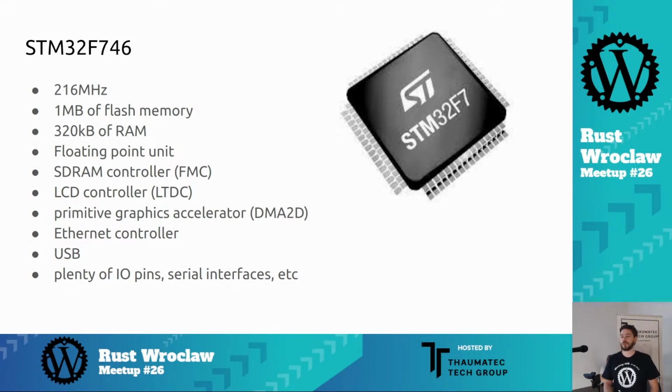So, for example, if you have an LCD with 16 pins to address the pixel color, you would normally use 565 encoding, which means you have 5 bits for red and 6 bits for green. This is because human eyes are most sensitive to green, so you have this extra bit of space to make it a bit better, and then you have the last 5 bits for the blue.